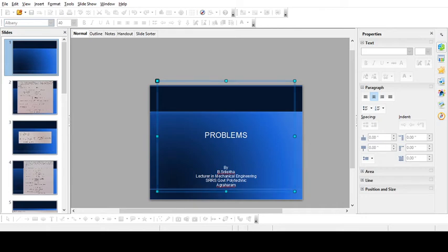So you'll get change in length as 0.0428 mm. Next, strain in the y-axis. So ε_y is equal to minus σ_y by E minus σ_x by mE, because the effect of both is a compressive force.